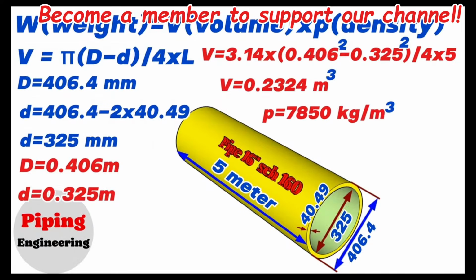Now let's write this information in the weight calculation formula. Weight equals volume 0.2324 cubic meters multiplied by the density of the pipe material, 7,850 kg per cubic meter. Using the calculator, we find that 0.2324 multiplied by 7850 equals 1824. So, we found that the weight of the 16-inch Schedule 160 pipe in our example will be 1824 kilograms.